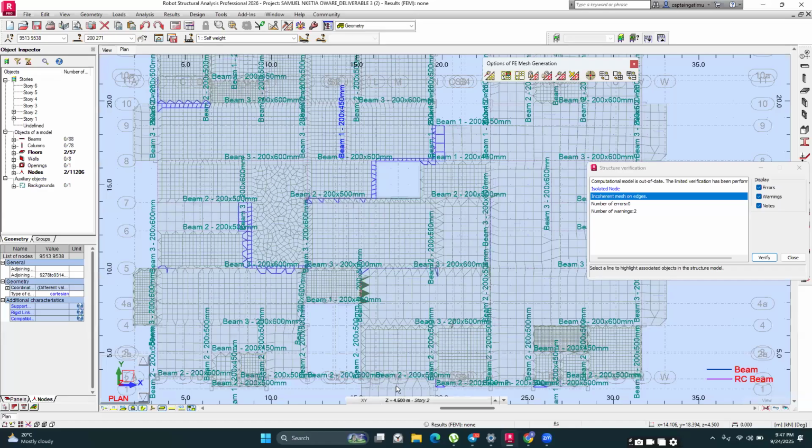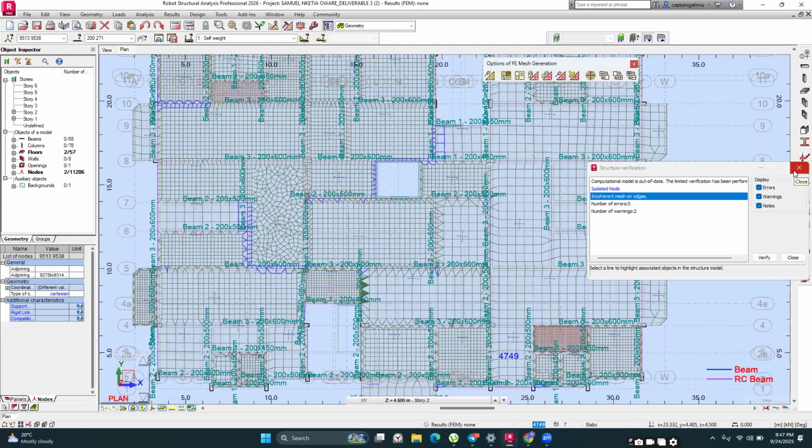Yes, engineer, I've taken notes. Okay, so it's that simple. Just select two slabs, delete the mesh locally, and then generate a mesh for those two slabs only. It's majorly due to the meshes not being continuous, or the software having a challenge with trying to mesh those areas. So you can just rerun them, and then it'll be good to go. Okay, noted, engineer. You're welcome.